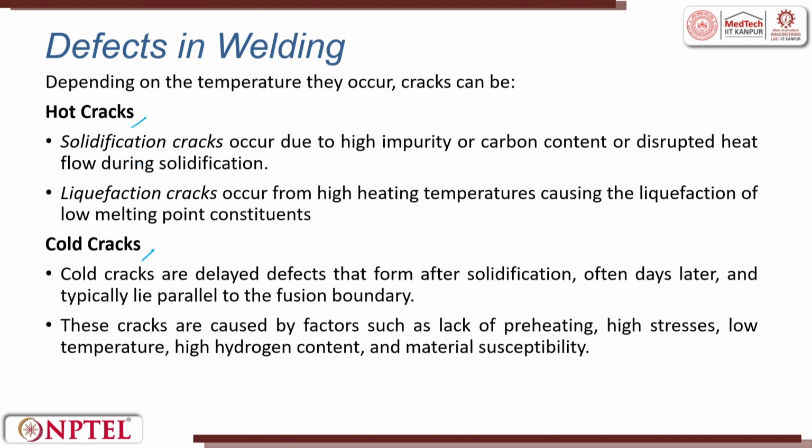What is a hot crack? The solidification crack, which occurs due to high impurity or carbon content or disrupted heat flow during solidification, is called hot cracking. The liquefaction crack occurs from high heating temperature causing the liquefaction of a low melting point constituent. So this is called a liquefaction crack. In solidification, the flow does not happen properly, there are impurities, and then solidification happens.